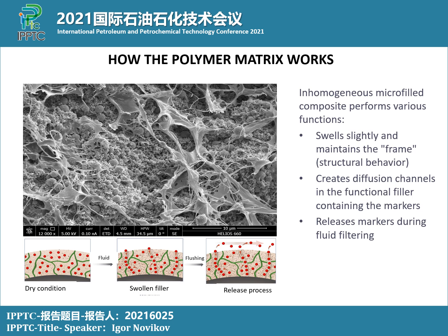And the important thing is that if there is no flow, the markers are not released. They stay at the surface of the polymer matrix and don't go anywhere. That is the main thing which gives us information if there is any flow from any port or not.